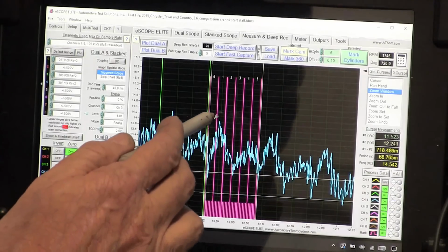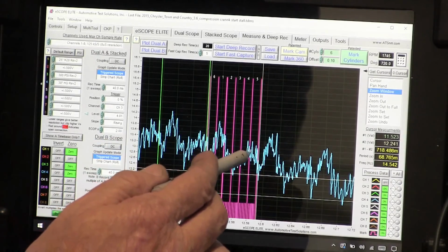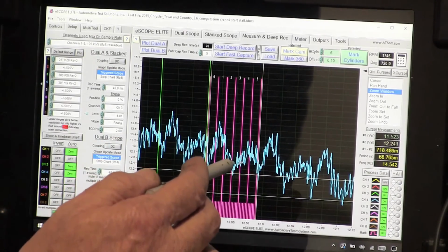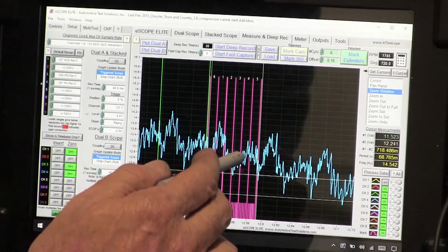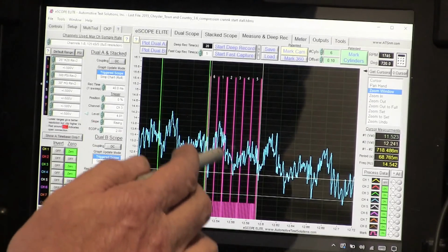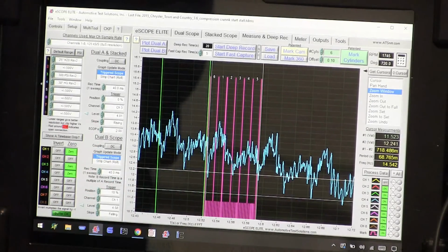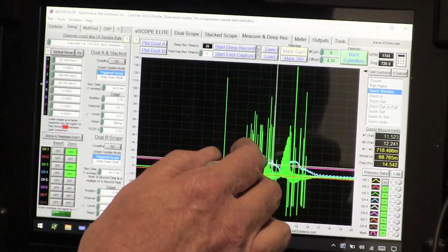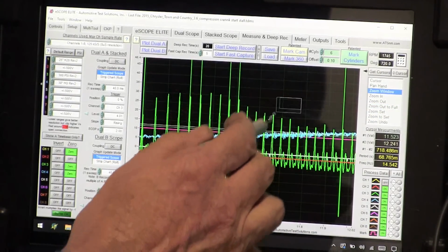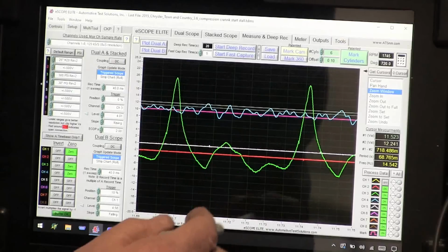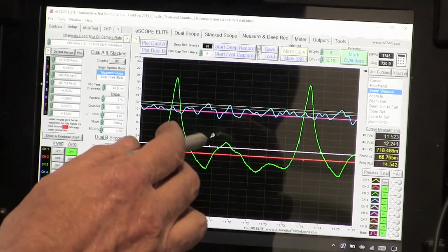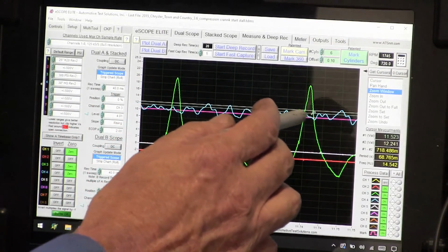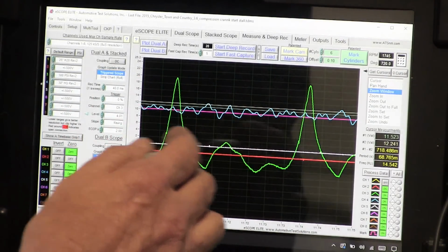See where when one opens it just loses all the vacuum and it never really recovers it. We're not recovering on 3 or 5. We lose the vacuum and then we're not pulling back up. But we definitely have no pressure in this cylinder to speak of. I mean, this is really, really low. But I don't see where when I come up on pressure I'm blowing the waveform down.